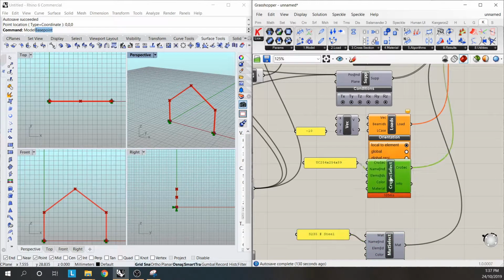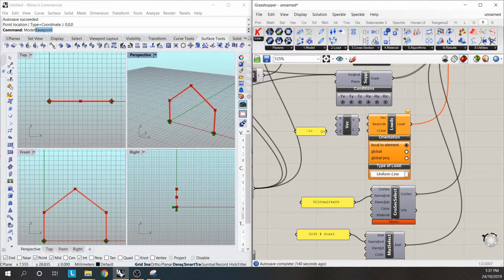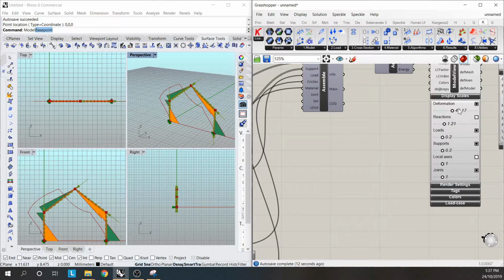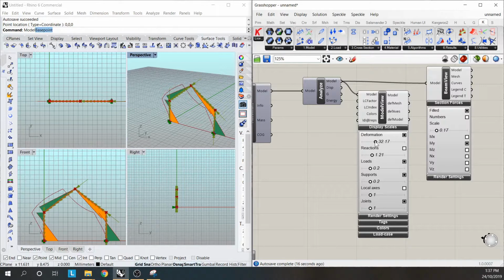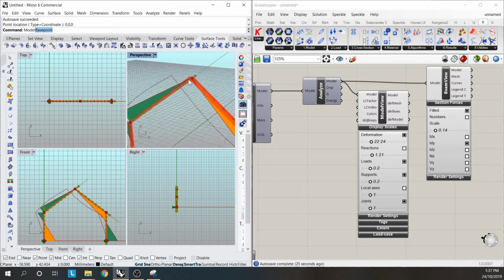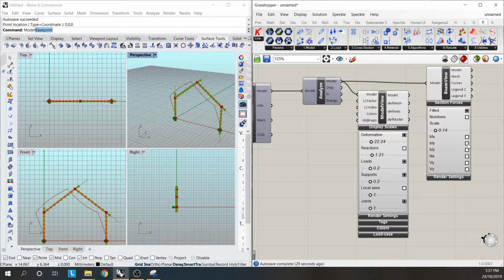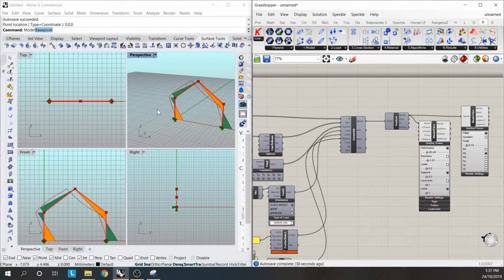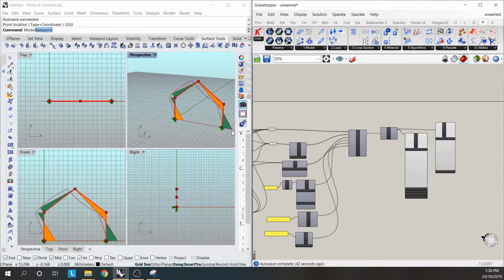let's go down a bit, give us some space, and I want the vector to be in the X direction. I'll leave it as -10, that's fine. So this will be the deflected shape due to wind. Now I'll just adjust the deformation down a little bit and the scale of the forces, but that should look logical. With a fixed portal frame, with wind acting in the negative X direction, those moments look correct to me.